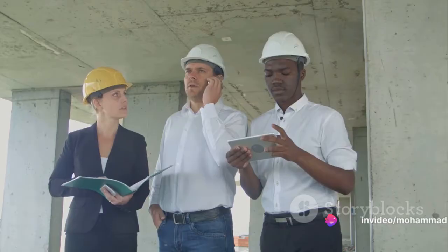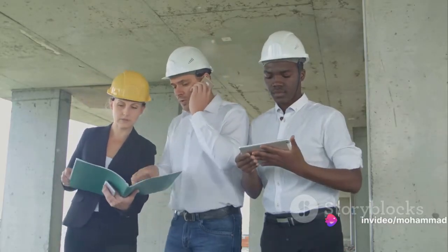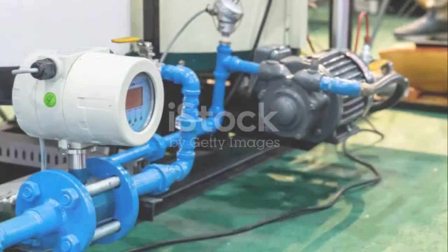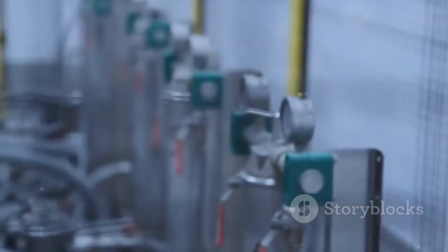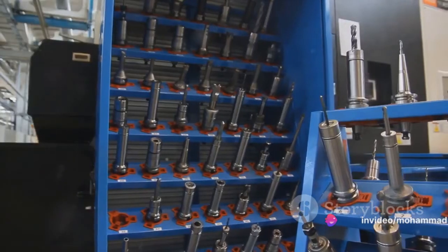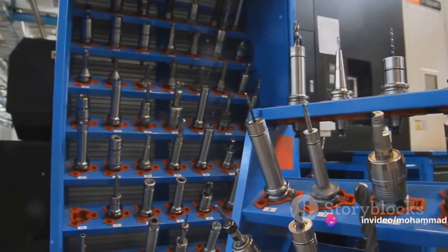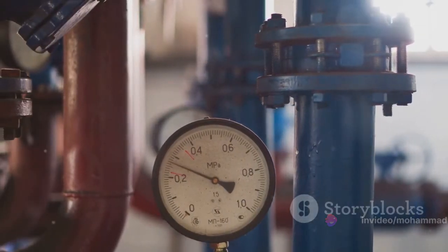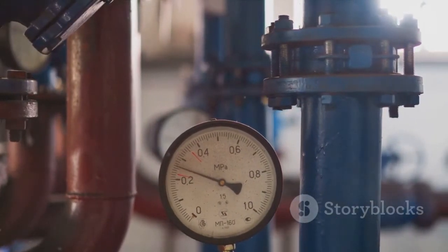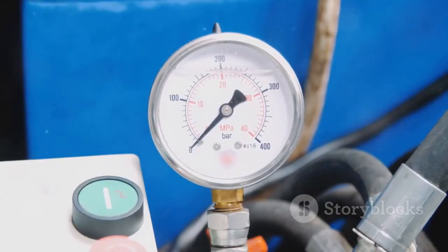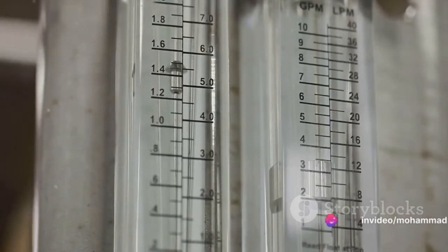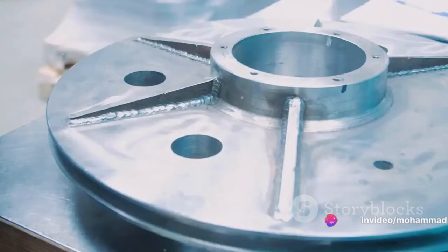Remember, the key to mastering any complex concept is breaking it down into its simplest components. Now that we have broken down the process, let's summarize what we've learned. The journey begins with a differential pressure transmitter, or a DP transmitter, placed across an obstruction such as an orifice plate. This setup creates a differential pressure that varies as the flow through the pipe changes. However, this differential pressure does not directly correlate with the flow rate. It's actually proportional to the square of the flow rate.